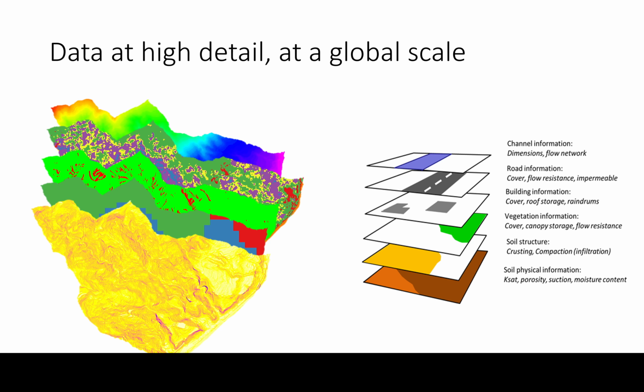And physically based models, anyway, models that relate to dynamic events on the Earth's surface are generally very data hungry. So there's multiple layers basically to the Earth's environment that we need information about to deal with that in an accurate way. The core of that, typically for flood modeling, is elevation data. Elevation data provides information about the most important guiding forces on the water, which is the gravitational and directional flow that is guided by the elevation itself. And the quality of the elevation model makes a big difference also on the quality of the flood model output.